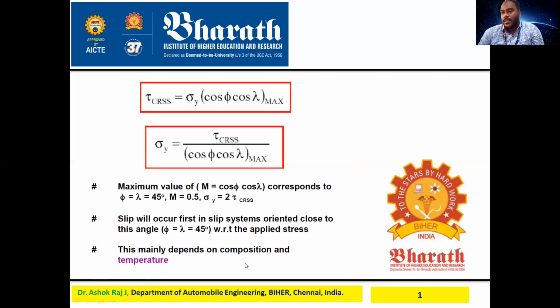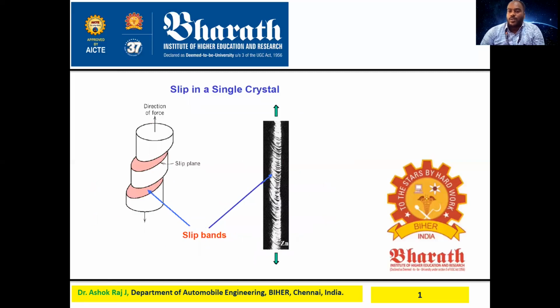Composition of what? Composition of your material. Whether your material is FCC, BCC or HCP matters, and whether you are working in ambient conditions or a high temperature environment also matters for the process. So if you see the slip in a single crystal, this is very interesting. Here, this is the direction of force. This is the slip plane. The pink color is the slip plane, and this is the slip direction.